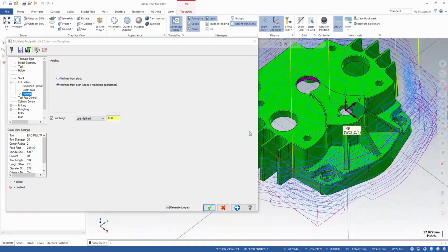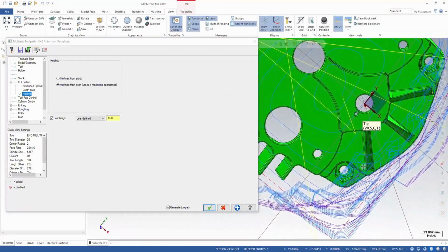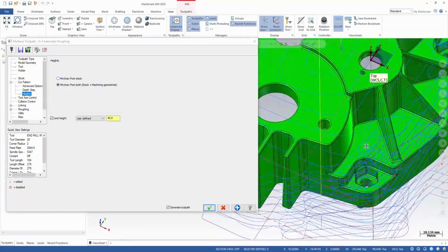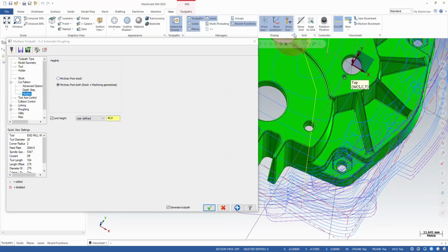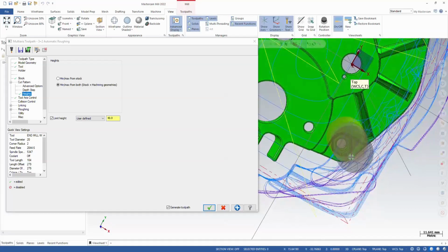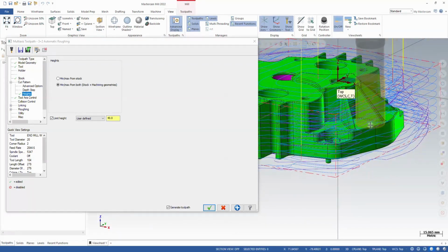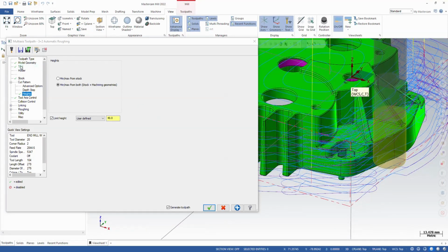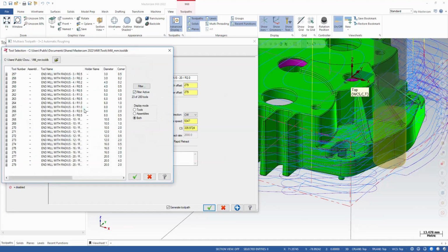So without leaving the window, regenerating the toolpath and things, I can see straight away that the tool I picked was too big. And this is another new thing that Mastercam added. It's a show tool, which is great because you can actually place the tool into some places on your 3D model and see if it's good enough, if it's not too big to machine the feature.